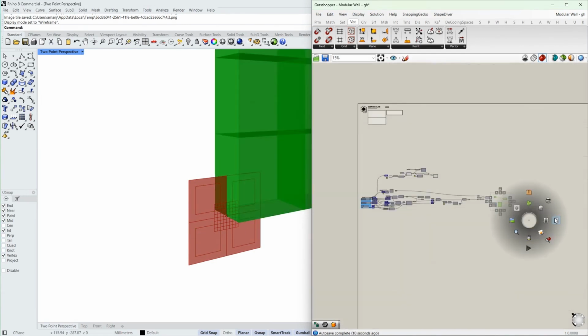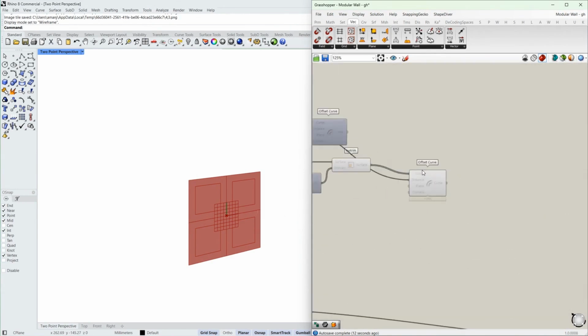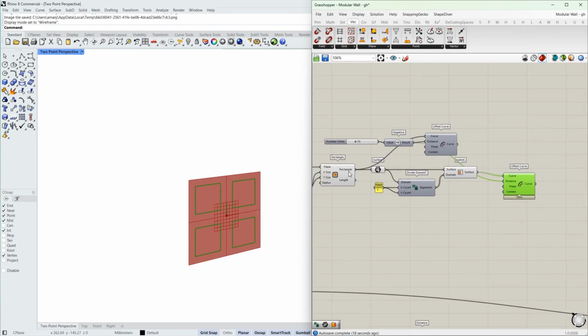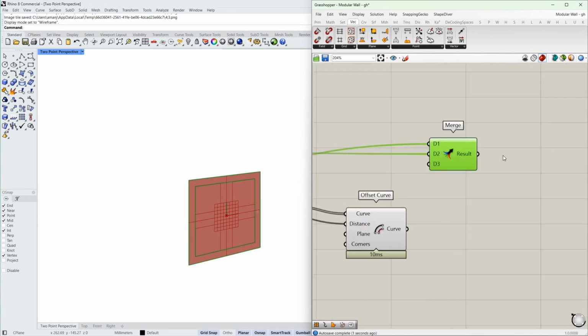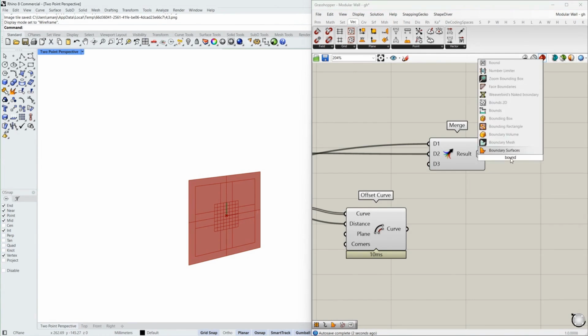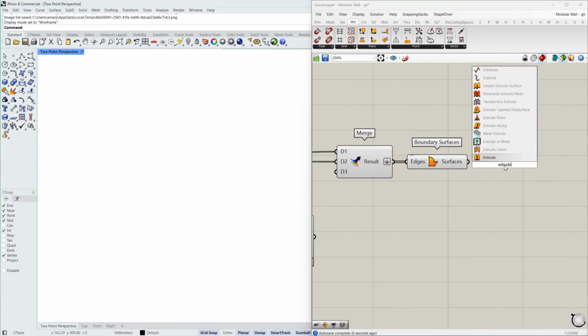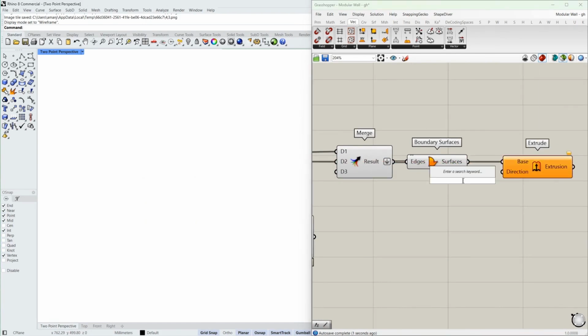And for this purpose, let me just hide this. Yeah. So I get these 4 curves. And now I have the main rectangle which is over here. I need to use a combination of the main rectangle and a curve. So this together, flattened, if I create a boundary surface, this is one module which can be extruded in the Z direction.